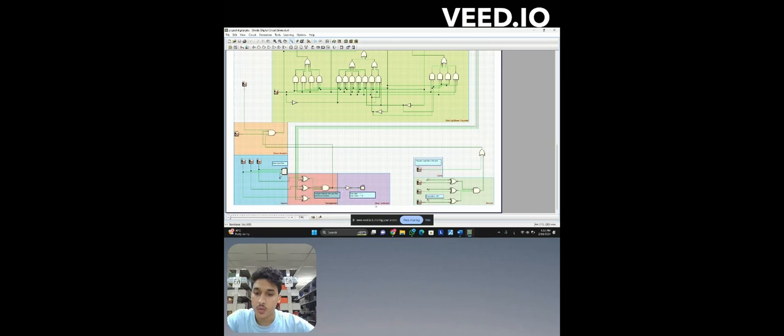Here, in the door indicator, we connect the output to the NOT gate for the door indicator. If it's zero, that means the input and the current floor are equal, so it's not working. So we come here to the NOT gate, which will convert it to one.